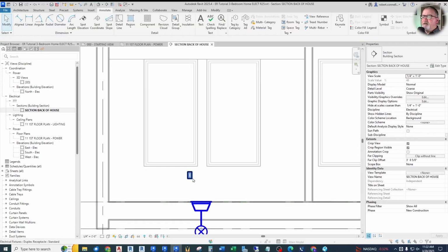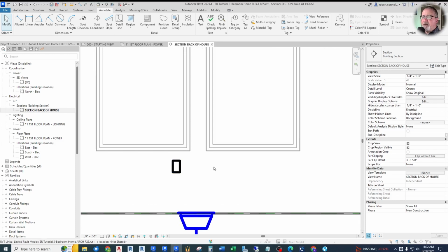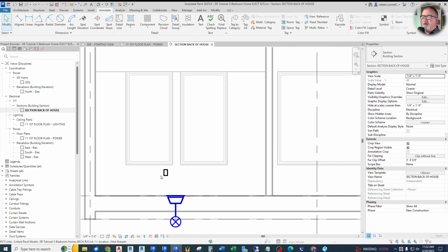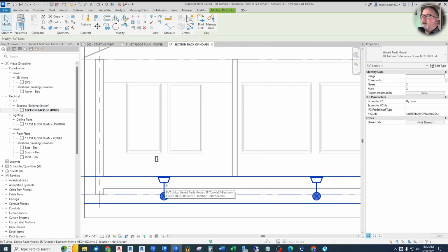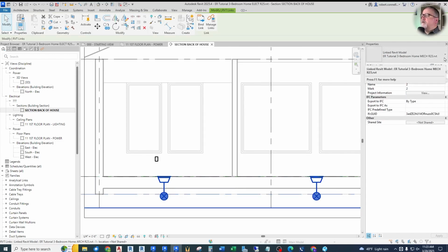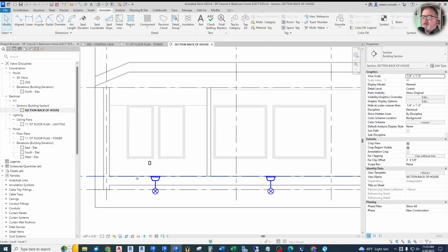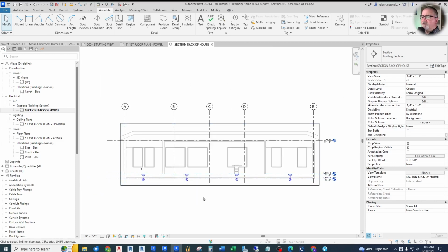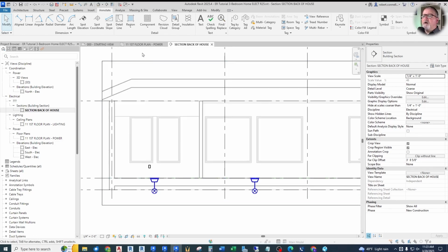Now, what we see is that our receptacle is mounted up on the wall. That's our 3-dimensional symbol. It's a cover plate that we see on the wall, and it's below these windows. So we are okay to mount this under the windows. We're also seeing some blue stuff here. What's this? This ends up being part of, click on it, the mechanical model Revit link. And these look like some ductwork and maybe some diffusers, some floor grills. And so that can be used for coordination with our electrical model if we have some interference or clashes. But our basic reason for this is to see that wall. Now, what else can we do?